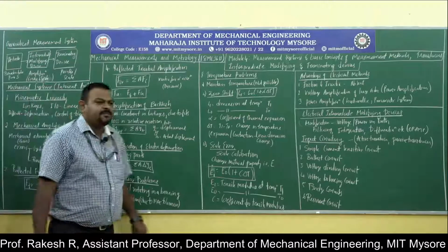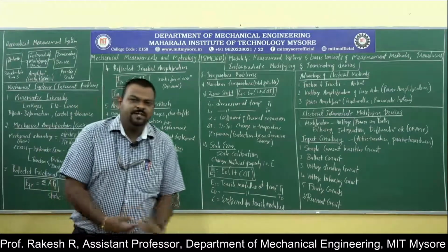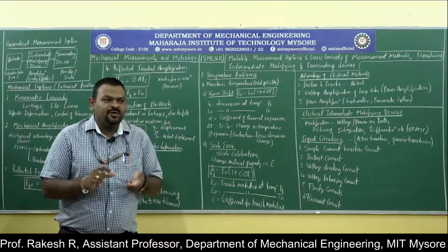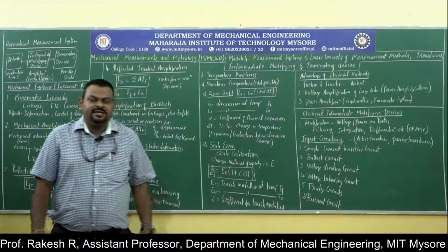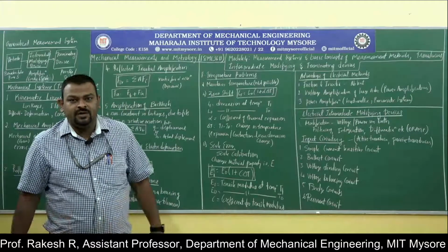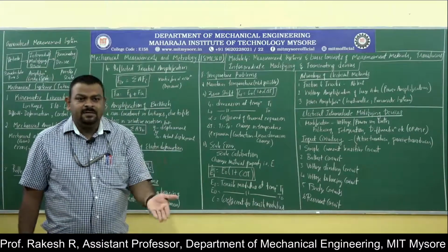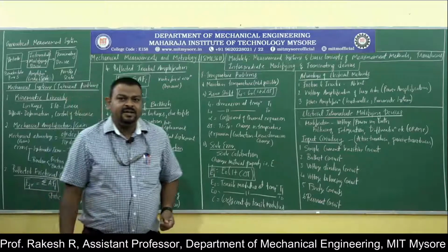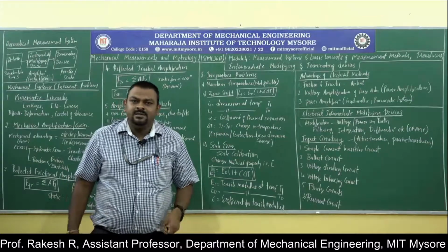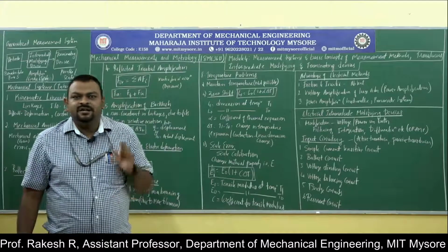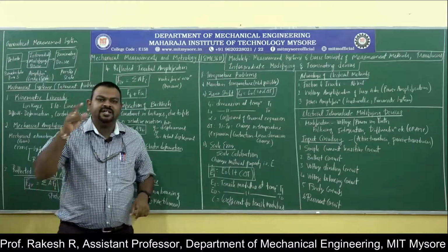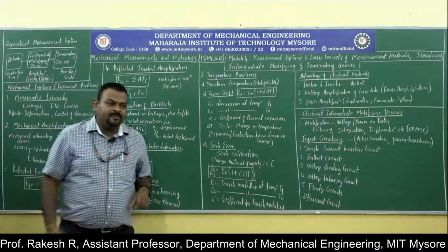Then next, tolerance problem. In metrology and measurements, if there is any tolerance problem, then the screw or fit you cannot obtain easily. Suppose you take an example of assembly of an M20 nut with an M20 bolt. If I take an M20 nut in India and an M20 bolt in Japan and assemble them, they will get assembled because there will be a convention, a standardization they will be following. This process is nothing but interchangeability of parts.